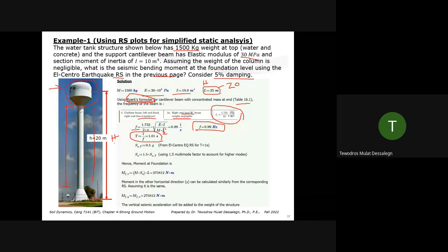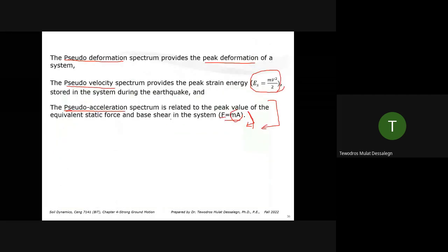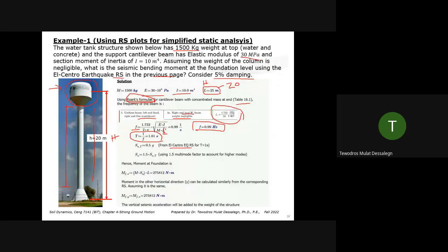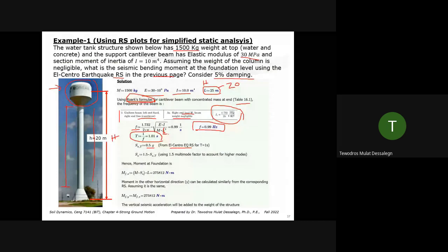you can get the acceleration. Go to the El Centro or the quick plot we talked about earlier, right here. With 1 second, get your value for 5% damping. Somewhere here, and I may not be exact. So get the acceleration around here. The acceleration is around 0.5 g.